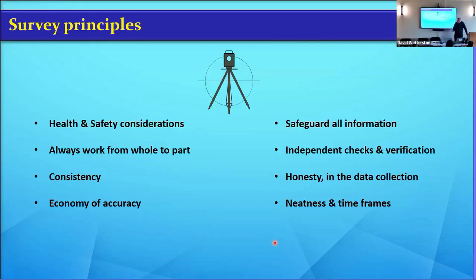Being honest, I'll survey stuff. And if you look at any of the field sheets, when we had COVID, again, I couldn't teach you guys. So I thought, well, how do I demonstrate what surveying is all about? So in the back of my garden, I surveyed it by taping. I surveyed it by chaining offset. I surveyed it by tachymetry, 3-stadia tachymetry, which is what you use the level with. And then I surveyed it with a total station. And I think I might have done it with GPS, but I certainly did it with a rotating laser as well. And I compared all that information to see how good it was.